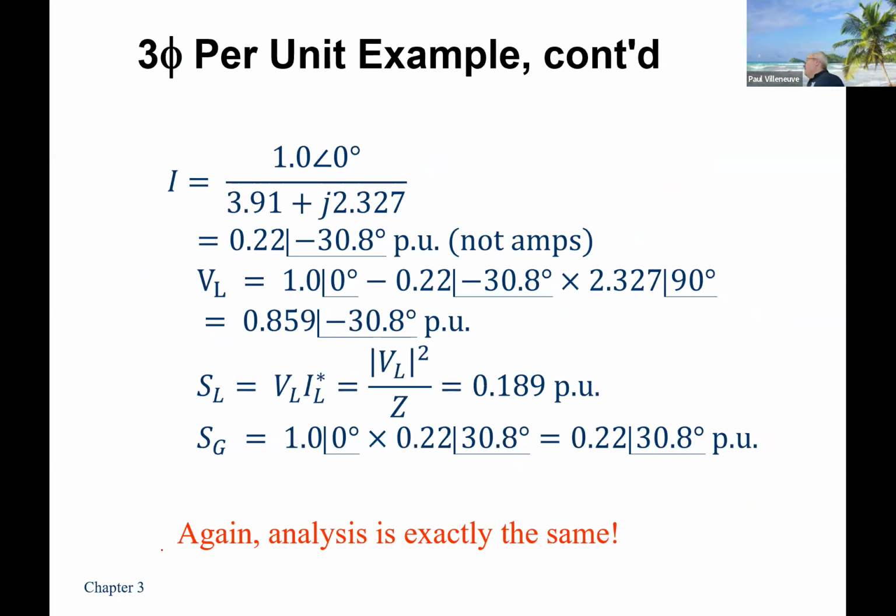Because our system here is all the same. Remember how before we had our load was 0.189? So that was, what does that work out to be, like 18.9 MVA or megawatts? Over here, I'm going to multiply by 300 MVA. Previously, I multiplied by 100 MVA. Since I have 3 exact systems, and each one of those systems is doing 0.81 times 100 MVA, I can say that the total of the 3 phases is going to be 0.81 times 300 MVA.